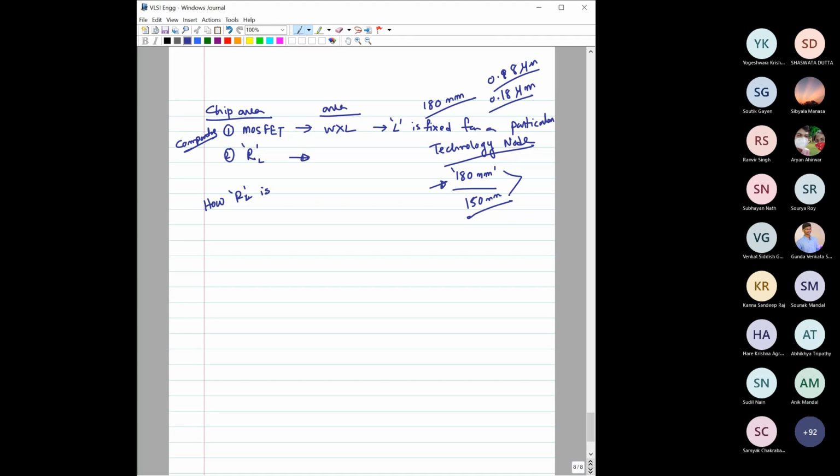So when you are going for bulk, the cost will be much lower compared to when you are going for a smaller quantity. So for smaller quantity, it's advisable you go for a bit higher gate length. When you need bulk chips, then go for the smaller dimension.